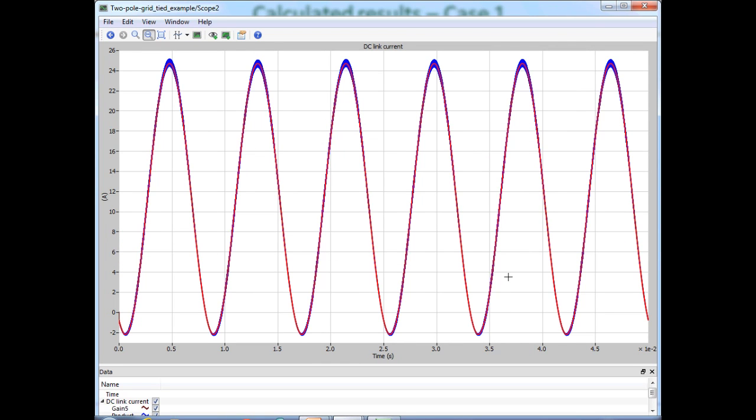Though it's not shown here, it's easy to see that there's a large DC component. Its value is I think 12 point something, and if you remove that, we end up with just the 120 Hertz sinusoidal waveform with a peak of around 13 amperes.